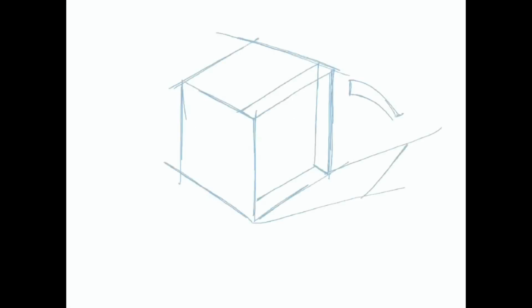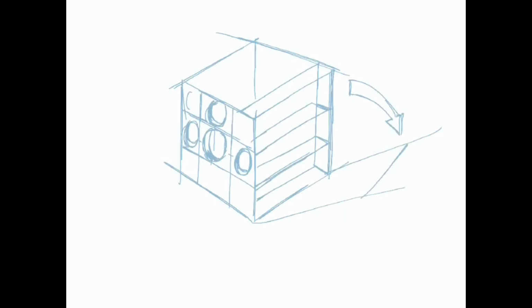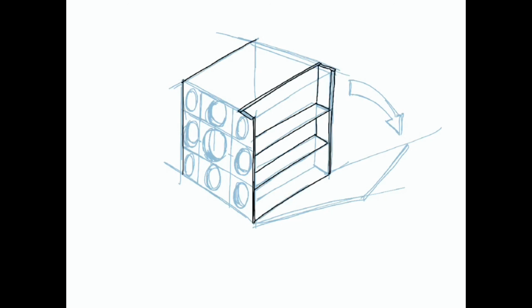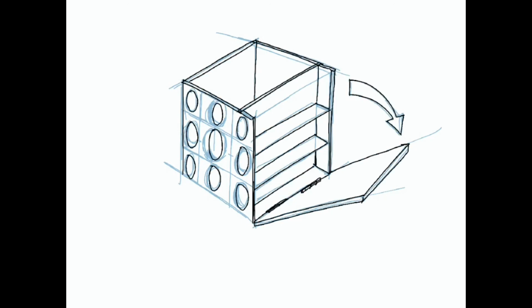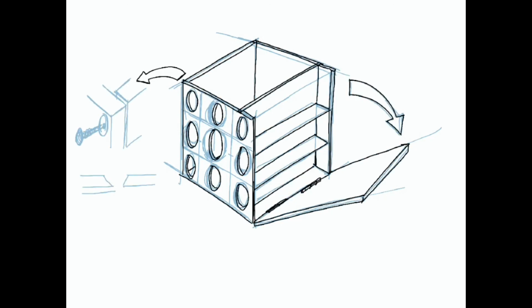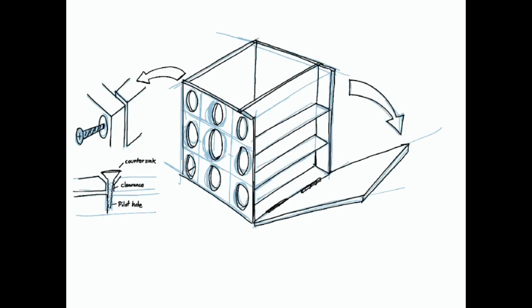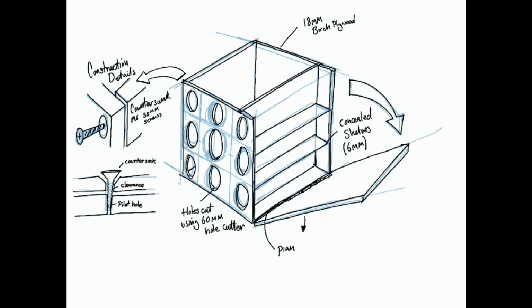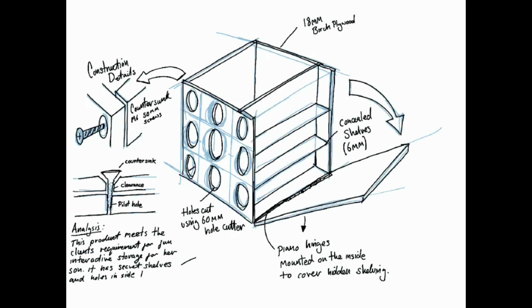So as with any sketch here, I'm going to start out in light pencil, working out the basic shape. Really, you want to be doing this in isometric, but it's still just a sketch, so I'm just using a rough isometric as the idea. You then work over the top in a fine black pen to get your details nice and clear. And notice that I've added those exploded sections I talked about. Make sure that the image has got an indication of the thickness of material as its development sketch, and then you can add your annotations as we just went through on the earlier slide.